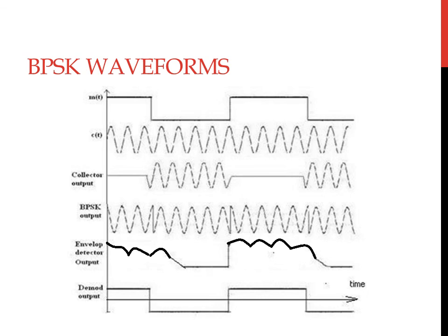With the reference voltage designed appropriately, it is possible to demodulate the signal, and the demodulated waveform will be a saturated value which is equal to plus or minus Vsat, equal to plus or minus 14 volt, if we use a dual supply op-amp of 15 volts.